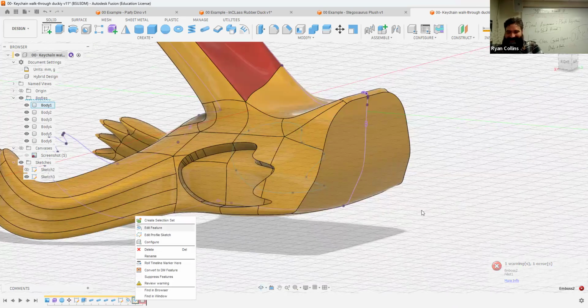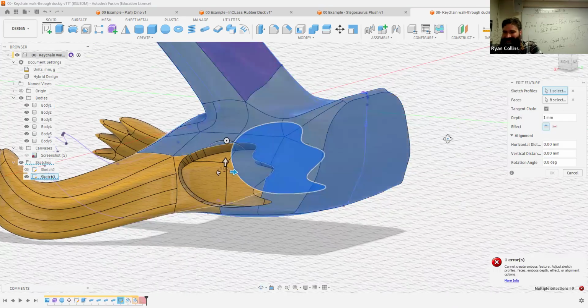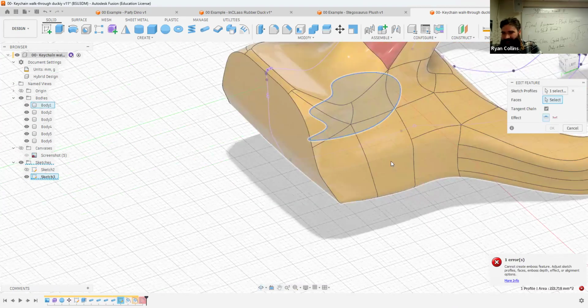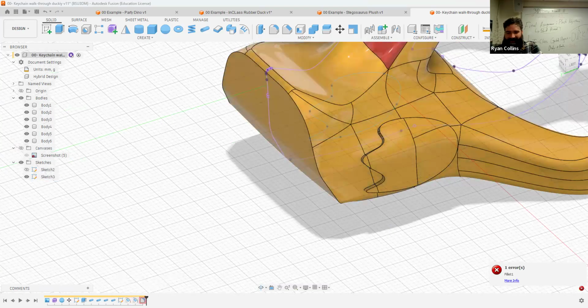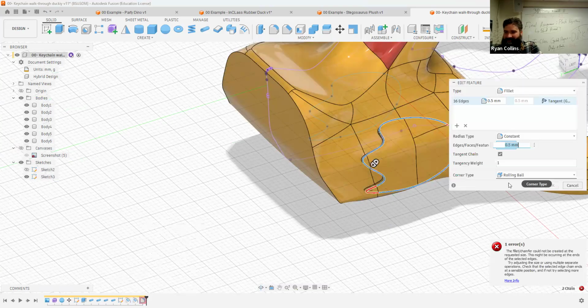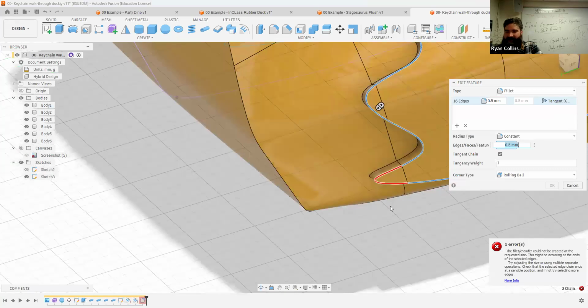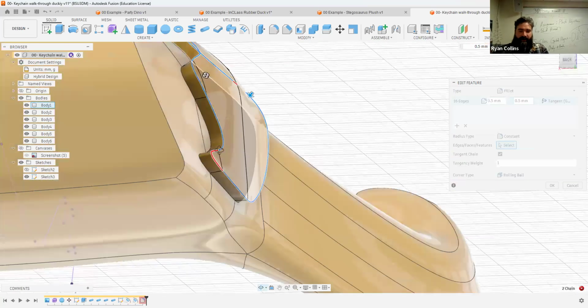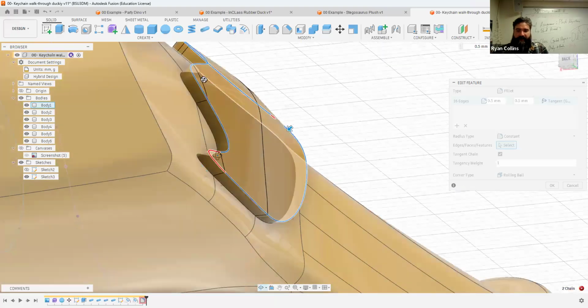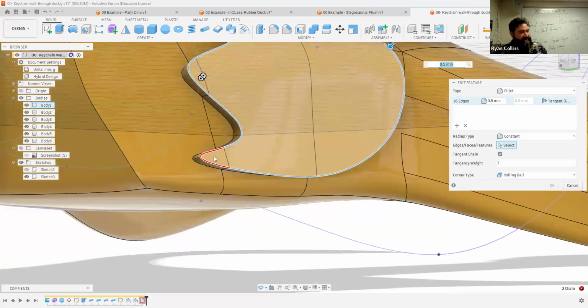Let's try reapply to the other side. That has wings. Working. I mean, that exists. And reapply my fillet. No, they have wings and fingers. So this is where one of the issues can come in with fillets. This is too sharp of a corner for it to apply. So you could either go back in and adjust the sketch or adjust the dimensions of your fillet.